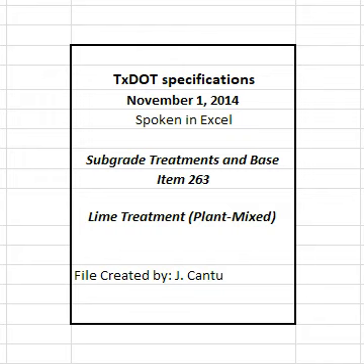5.4 Ton. Lime-treated base will be measured by the ton, dry weight, in vehicles as delivered on the road. The dry weight is determined by deducting the weight of the moisture in the material at the time of weighing from the gross weight of the material. The engineer will determine the moisture content in the material in accordance with Tex 103E, from samples taken at the time of weighing. When material is measured in trucks, the weight of the material will be determined on certified scales, or the contractor must provide a set of standard platform truck scales at a location approved by the engineer. Scales must conform to the requirements of Item 520, Weighing and Measuring Equipment.